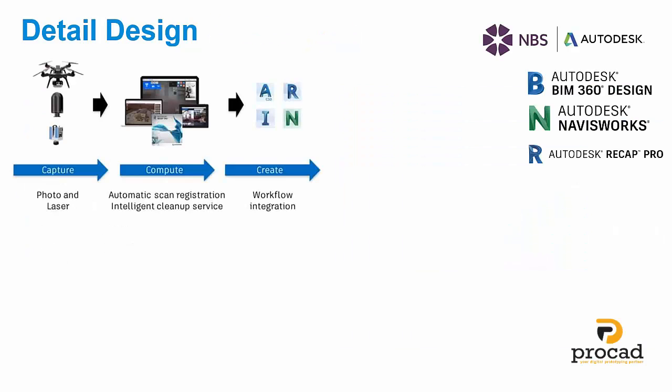So looking at the detailed design, I suppose from a surveyor's point of view, the likes of laser scanning and drone scanning, being able to capture that information, being able to push that information using the likes of Recap Pro, bring that into Revit, if it's the site context or your site topography or existing buildings, you're able to bring in that as a point cloud, and then you're able to convert that within Revit into intelligent building objects as well. And this can help inform you, and it's better collaboration between architects and surveyors and engineers as well for existing site conditions.